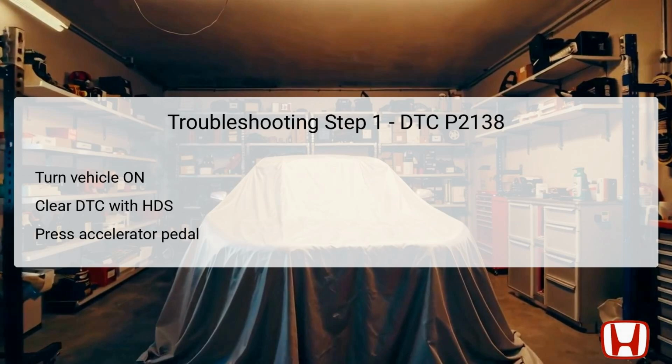The first step in troubleshooting DTC P2138 involves turning the vehicle to the on mode without starting the engine. This allows the vehicle's onboard diagnostic system to perform necessary checks. Following this, the diagnostic interface known as HDS, Honda Diagnostic System, is utilized to clear the detected DTC.